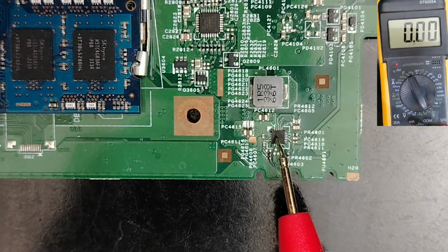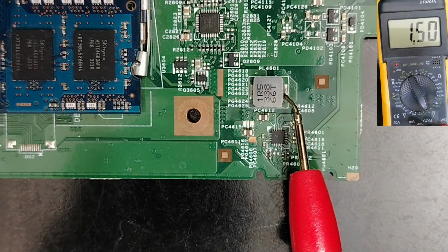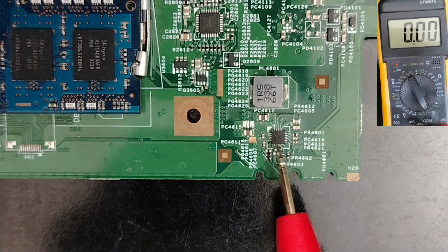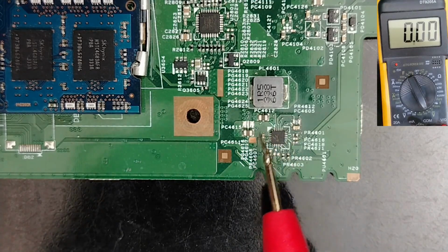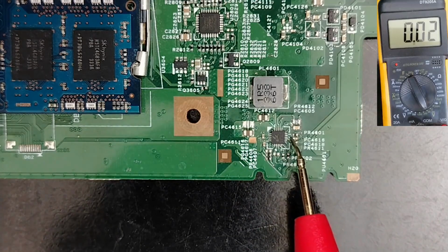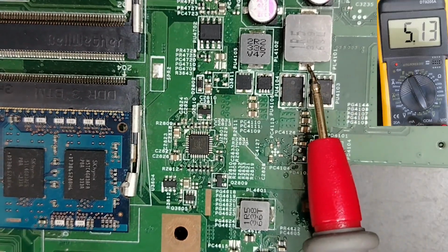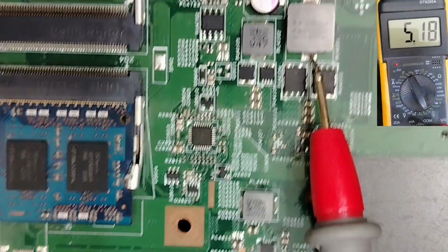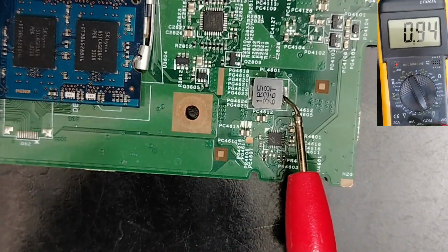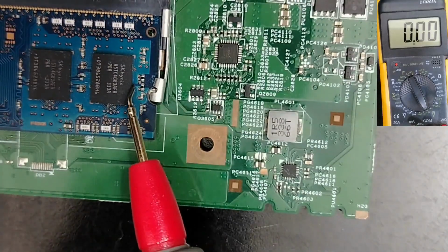This is basically the control IC that generates this voltage for the RAM. But what is the working voltage for this IC? If we check, we're gonna find 5 volt or 3.3 volt. So let's check the ceramic capacitors around it. This one, for example, we have 5 volt. Okay, guys, if we check this one also, we have 5 volt VCC. So here, guys, the 5 volt is the input or the working voltage for this IC in order to get 1.5 volt. Without this voltage, the RAM will not be fed.